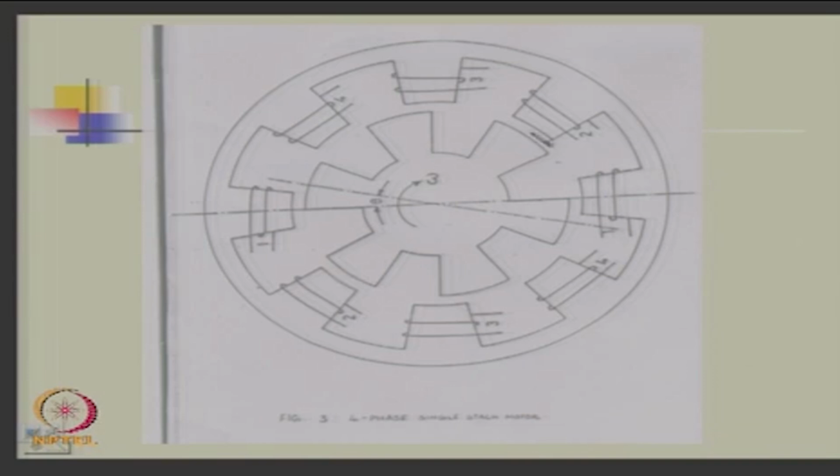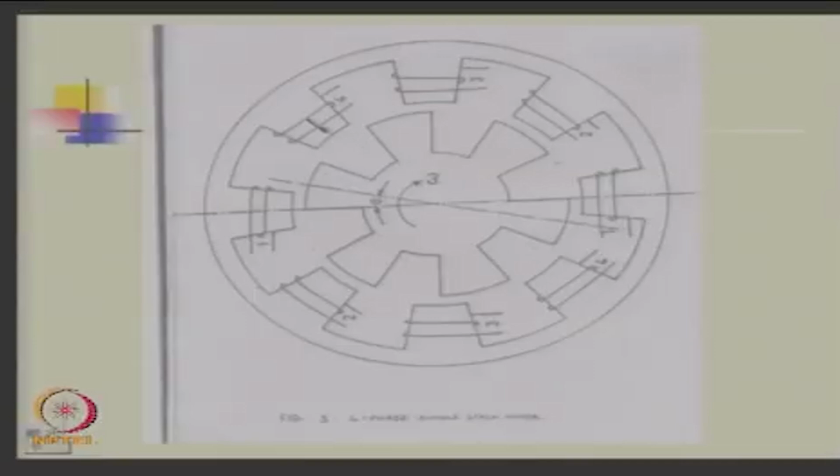When do you find saturation? You find saturation if the magnetic path has more iron, only in iron, not in air. So in the unaligned inductance there is no saturation, it can be considered linear, and it does not depend on the winding current, okay. Is it clear? Any doubt till now? So we have covered the construction, requirement of switching, inductances, inductance profiles and other things, okay.